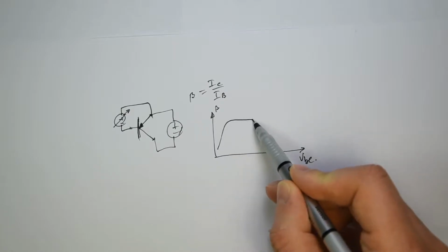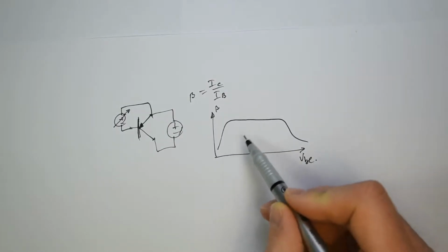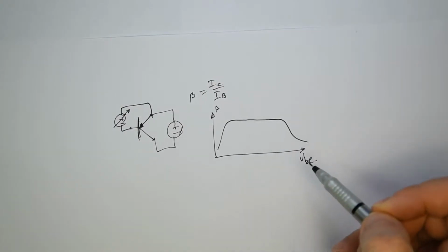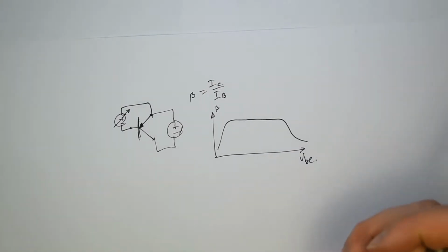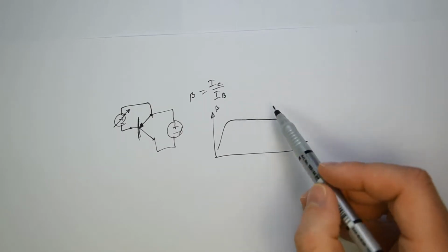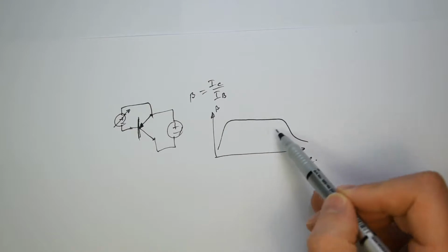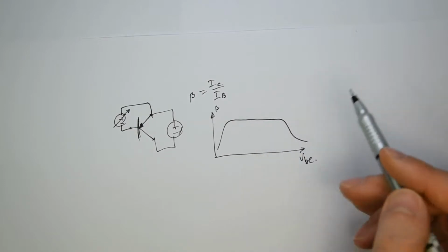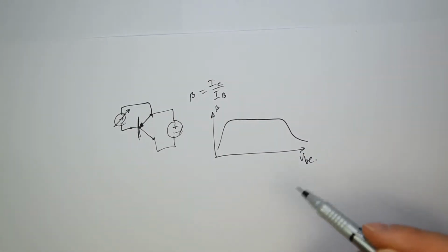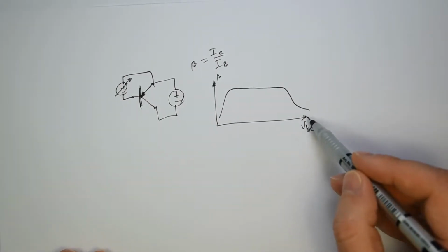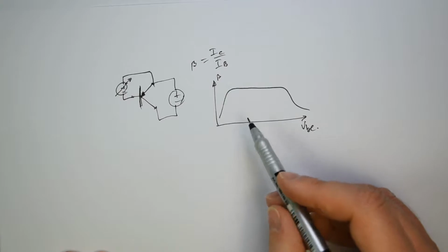It is something that is flat between certain VB voltages. And this is important because you need to have your operating point somewhere into this plateau. The same thing can be seen in a different way, because now we have the plot versus the voltage, but let's plot it versus the current.